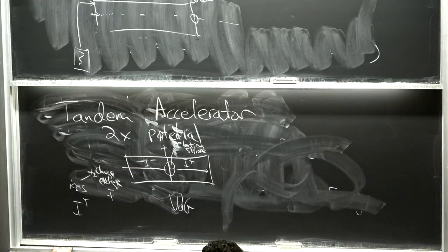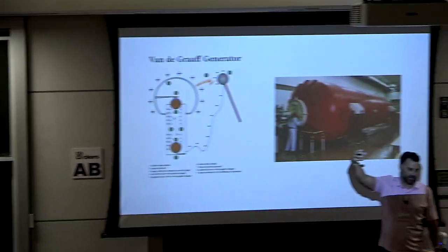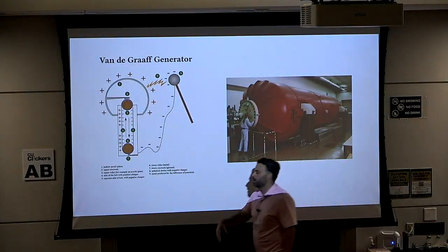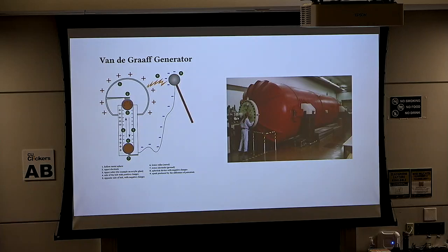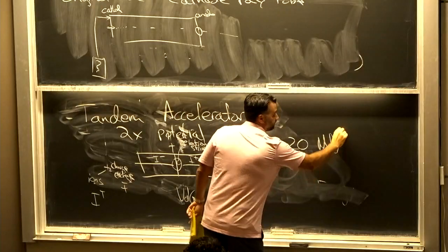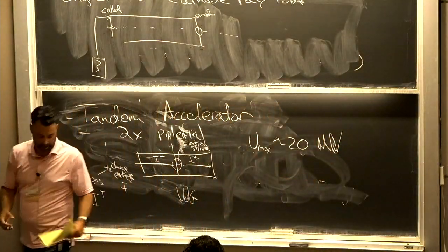Now, the problem is you can actually get a little bit more than a megavolt. Okay, I'm just always saying megavolt is the rough scale for this. With Van de Graaff generators, if you use these tandem Van de Graaff generators and you put an inert gas that's pressurized in this, you can actually increase the breakdown voltage, so you can get higher. And Van de Graaff generators can get you roughly up to a Umax, let's call it 20 megavolts, okay, in that neighborhood.